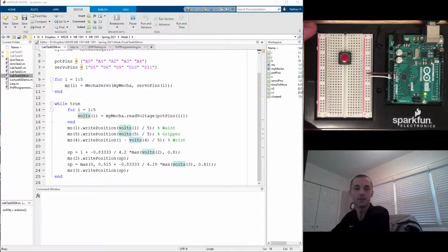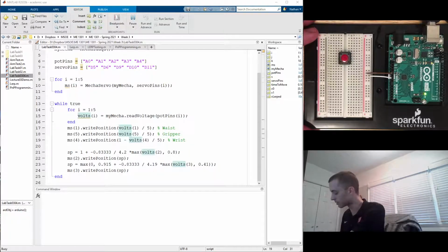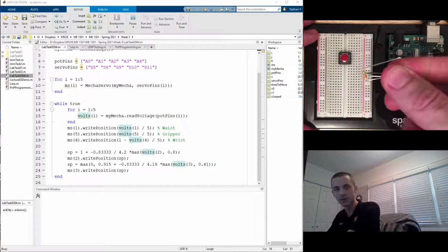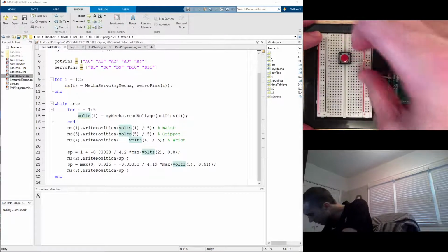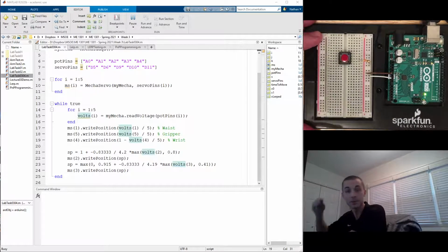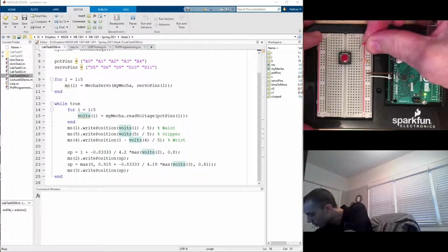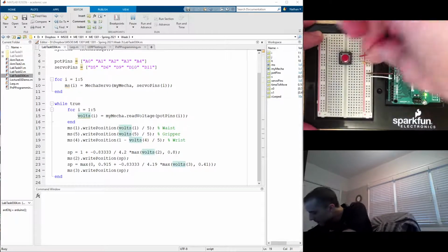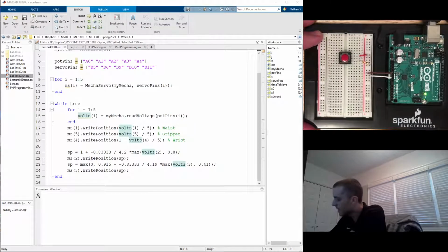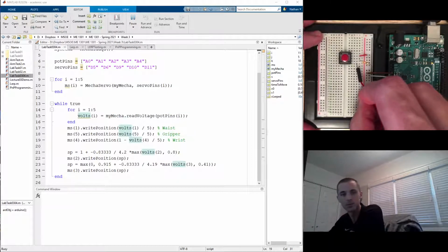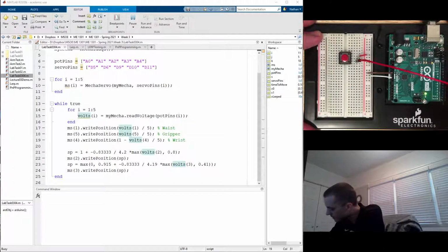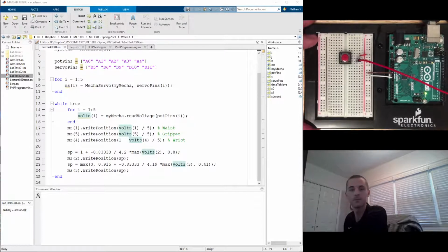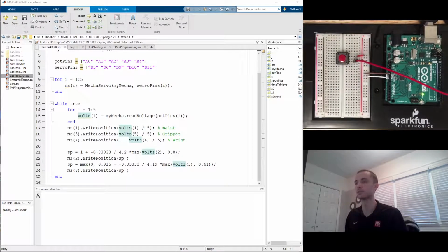And then to the button, I'm just going to do a pull down resistor. I picked one of the 330 ohm resistors. That should work fine. Going from the bottom pin to ground. And then on the other pin, the pin on the top for the switch, I'm going to use a wire to connect it to 5 volts. And then from the side that has the resistor pulled to ground, I'm going to put a wire and take it over to, let's say, D4. All right, so just a push button switch, and we can test it.